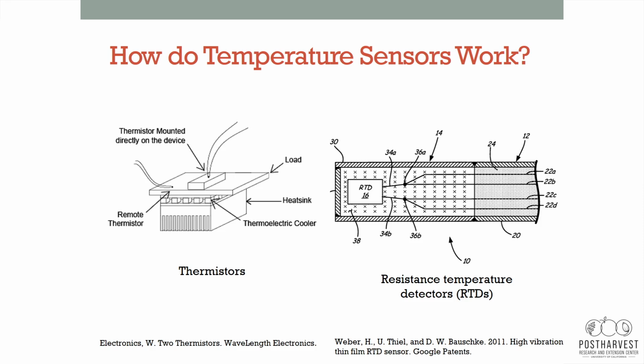And that's what typically is measured. And there are multiple ways. There are thermocouples, thermistors, resistance temperature detectors, and each of them has different accuracy rates, robustness, and so on. So you need to be aware that there's also a difference in pricing, that a typically inexpensive temperature sensor is not the best of quality.